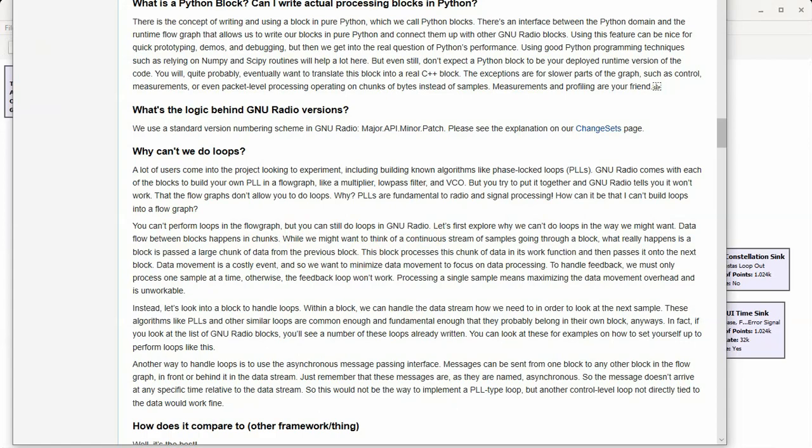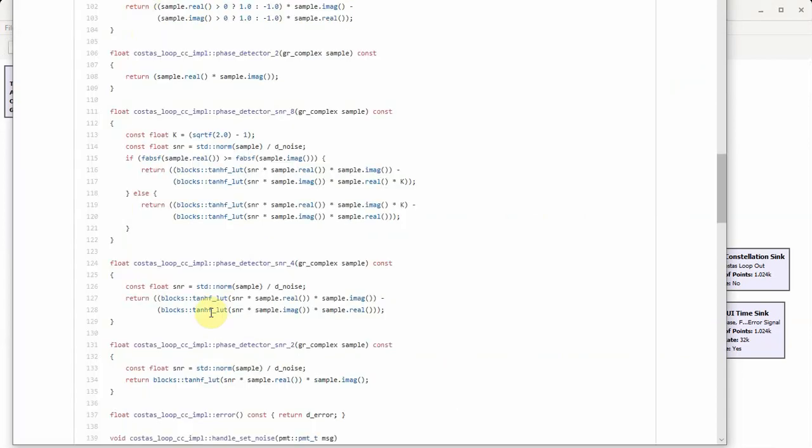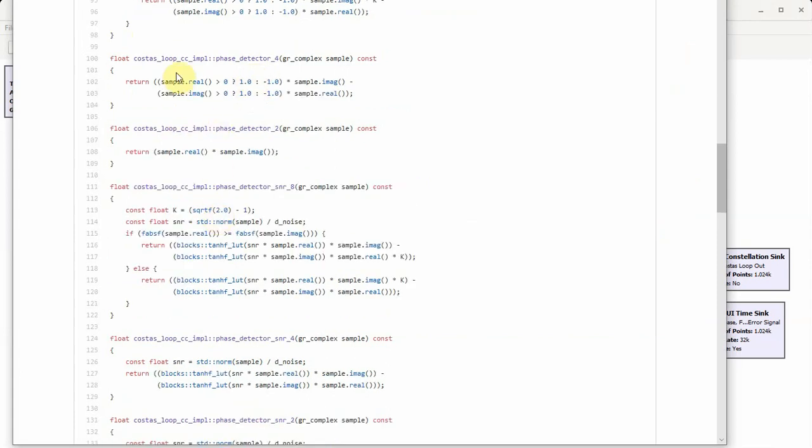For example, I can show you the Costas loop code on the website, and you can see here that once you break through these programming barriers, the phase detector is simply implemented through the same equation we mentioned in the lecture. So basically we are taking the sign of the I arm, here we are taking the sign of the Q arm, and multiplying this with the imaginary part and this with the real part. Taking the difference is just a simple phase error detector we have discussed in the equation. Similarly, for a BPSK Costas loop, we just multiply the real and the imaginary parts together.